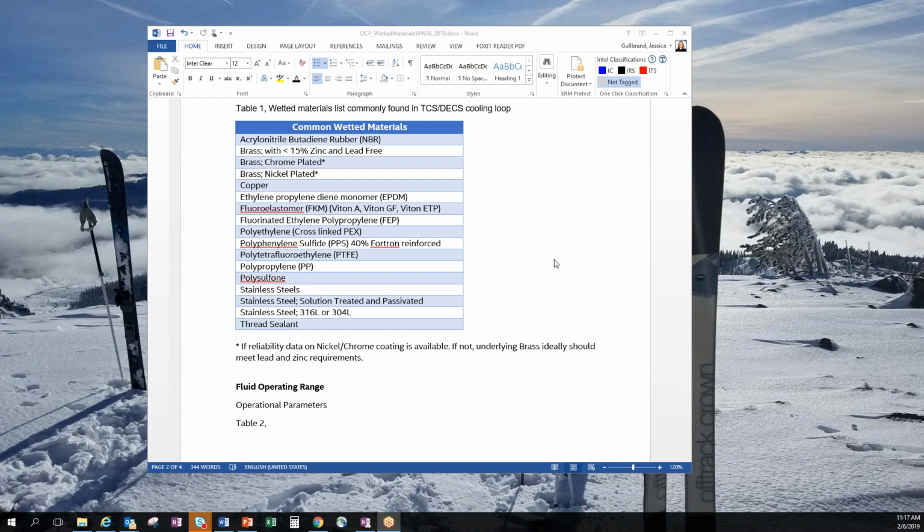Yeah. So I was thinking of referencing ASHRAE, saying if you need a more current list, here is an example. But at least this would allow fluid suppliers to talk about fluids that show material compatibility with the operating ranges and the common wetted materials that are in there. If you have any other additional wetted materials, then we need to evaluate those. But having a starting point, again, of not only focusing on water, but having water with additives, propylene glycol water, and then dielectric fluids, of at least giving the users a choice of what type of cooling fluids would work best for them.